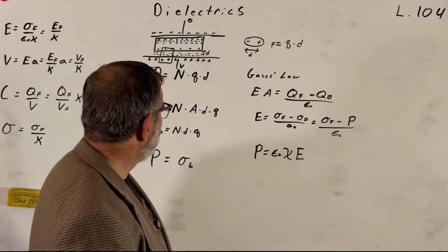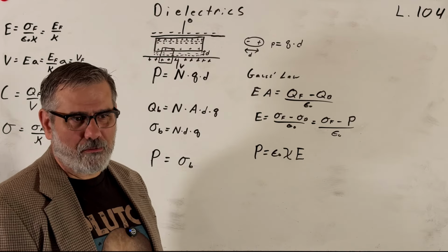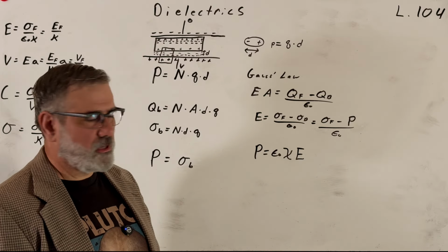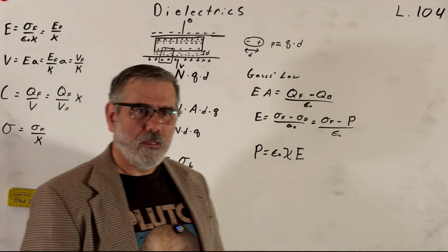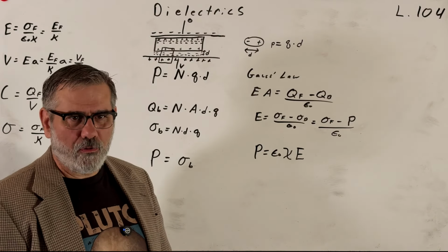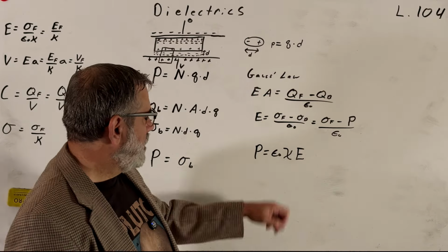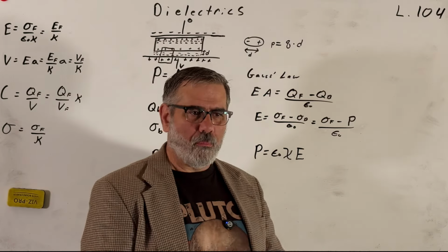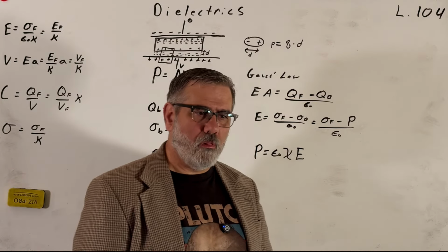Because the dielectric constant was telling us what's the increase in capacitance because of a dielectric material. And that was related to the polarization that was induced in the material, which is decreasing the electric field in between the plates of the capacitor. And this is supposed to be a measure of how easy it is to create a dipole moment in a material. Now in general, here I've shown it to be linearly proportional, okay?